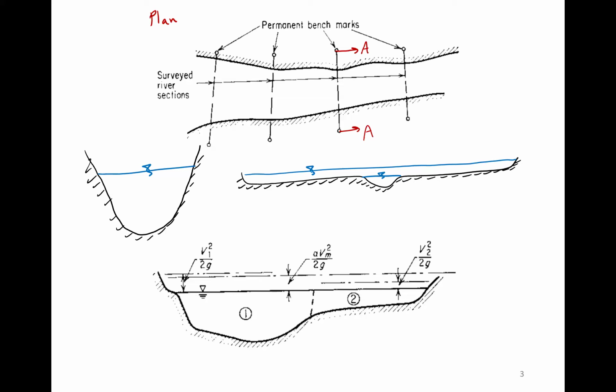Now, if you look at the section at the bottom, this one only shows the deep side of the channel, and then one shallow side. Now, as we said, at low flows, we have water levels somewhere here. And typically, we call this section of the channel the main channel. This is the deeper part. This is the part that's typically narrower in plan and active for most flows, including low flows. And then as the water level goes up, let me actually write it here. This will be our relatively low discharge.